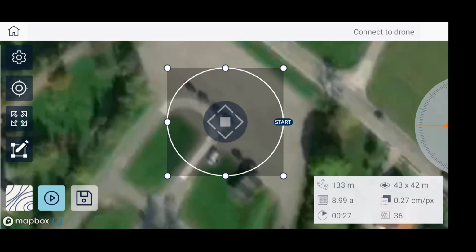Why I start with the highest circle is just because of safety. At 20 meters, probably there are no trees, no traffic lights or similar objects. You get a good idea where the drone will fly, even later on the second and third circle, which will be lower and the radius will be bigger. Then, if there are some trees or anything like that, you can stop the drone and do a manual flight in addition to get additional data and so on.